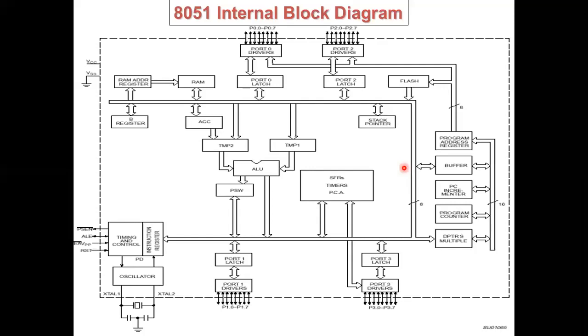Why are we using 8-bit registers as special function registers? Every register is represented by an 8-bit address, so we can access the register from the internal memory, and we have more clarity in the execution process. In the 8051, the termination of the program is an infinite loop, using SJMP $, for unconditional jumping. For repeating the process, it executes continuously.